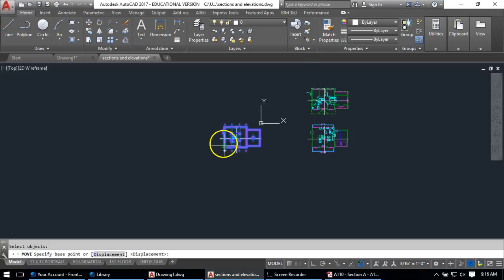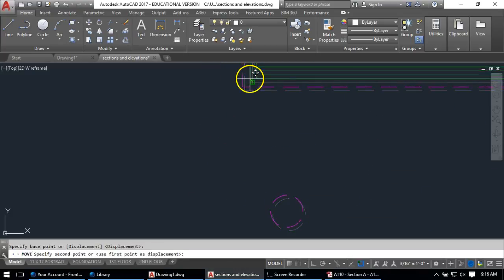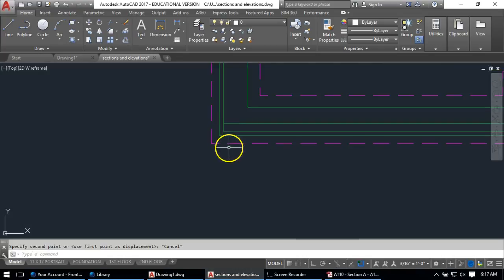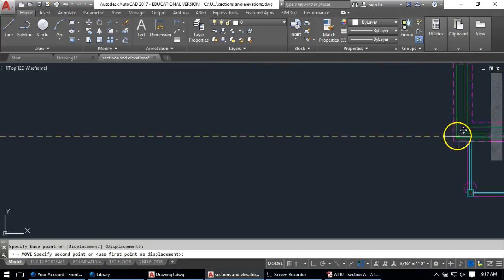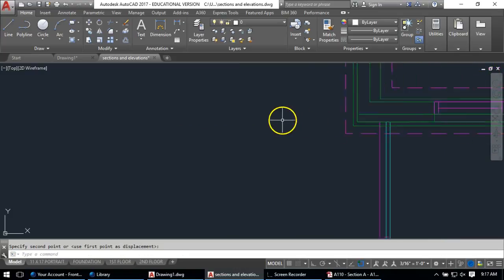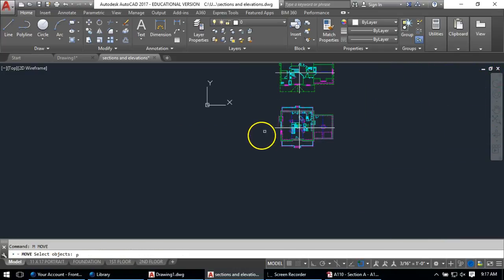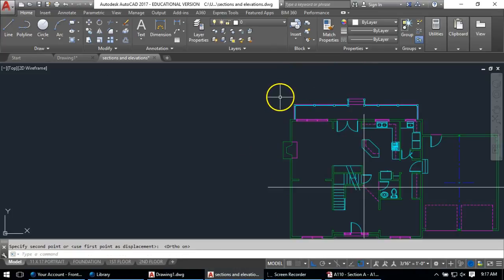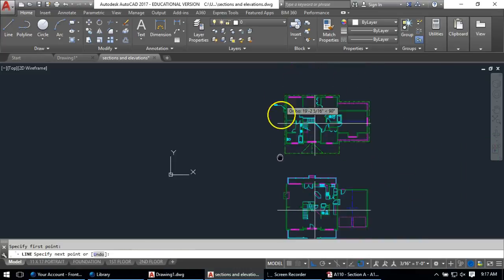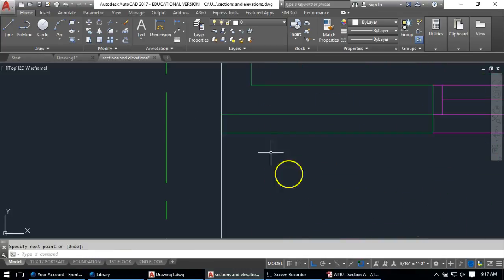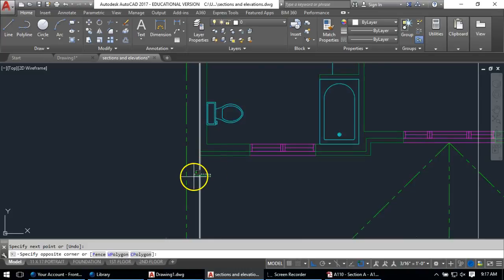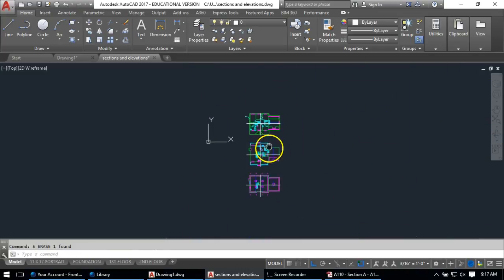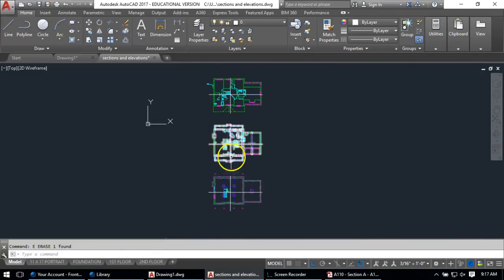And I'm going to do the same with my first floor. I'm going to snap from the corner. I want to be careful here because there's actually insulation, and the insulation is not aligned on my wall. All right, so I'm going to make sure I don't get that, and then move it straight down. Let me make sure my second floor, my vertical snap might not have been on. My second floor. I just want to verify it is. Okay, because you want to be very precise, you want to make sure it's accurate like this.